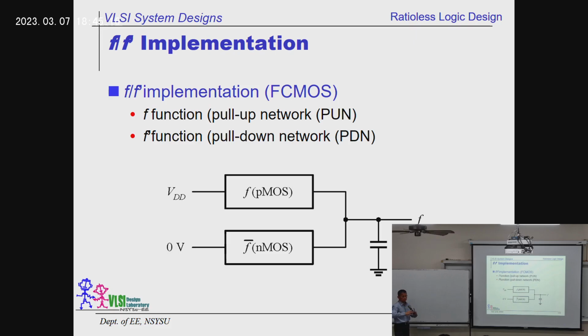Basically, you group all the PMOS devices on the top, where they are coupled to the power supply VDD, and all the N transistors are grouped together at the bottom, coupled to the ground or 0. In the middle is where the output is. That's the basic, very fundamental idea. If you know this, then you know one of the most efficient approaches to design a gate using transistors. Besides, we also talked about how to tune the size properly.